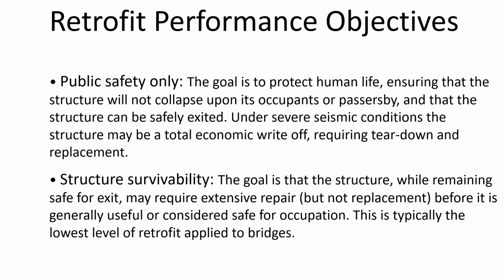Now, structure survivability. The goal is that the structure, while remaining safe for exit, may require extensive repair, but not replacement, before it is generally useful or considered safe for occupation. This is typically the lowest level of retrofit applied to bridges.